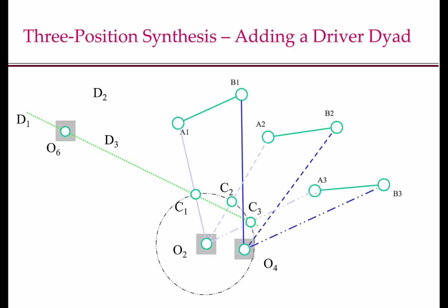Again, any point on this line C1, C3 extended will be a fixed pivot O6 for the driving dyad, and take a circle of radius C1C3 by 2, and the points at which it intersects are the positions D1 and D3 of the moving pivot of the crank. So here I will draw the crank at the position 2 so that the straight lines don't overlap. But O6D2 is my crank and DC or D2C2 is my link that is connecting to the link O2A.